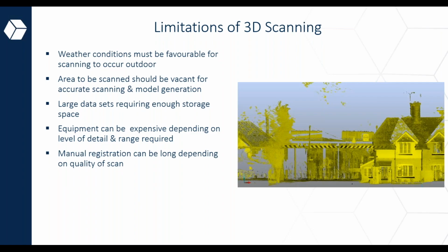Another little bit of a limitation is that after you scan your data or scan the relevant spaces, the individual scans or point clouds need to be aligned or merged. This process is basically called registration. It can be a bit time consuming, but it depends on the computational resources that you have available to you. Manual registration does require additional effort, but with the right expertise, it can be done very seamlessly and very accurately.